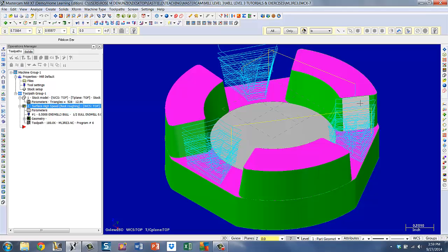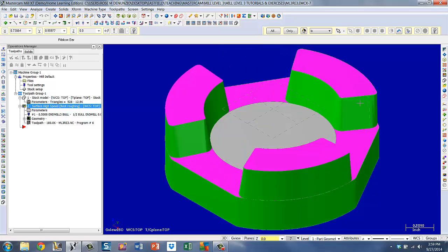Okay. Now I want to do that surface finish blend to do the floors first. In order to do those, that particular operation requires some lines to blend along with a drive surface and a containment boundary. It also wants some blending lines. So we're instructed on page 291 to put some blending lines in.